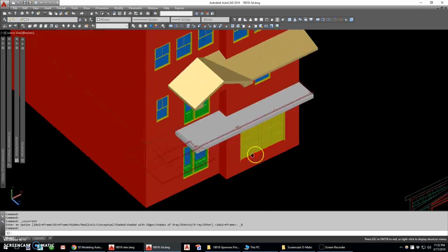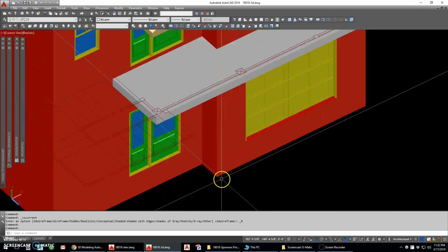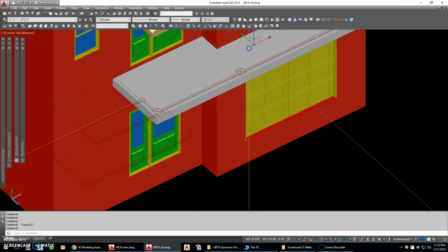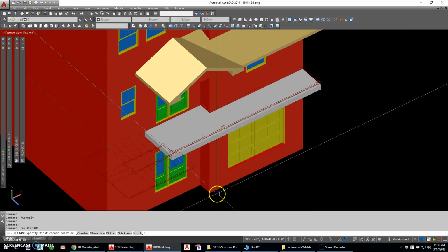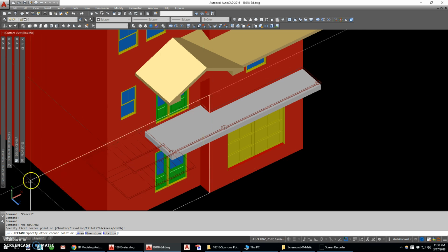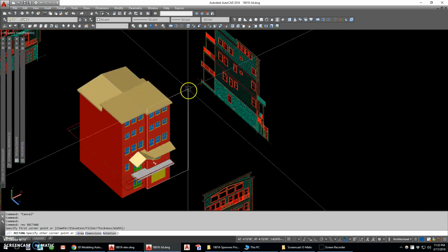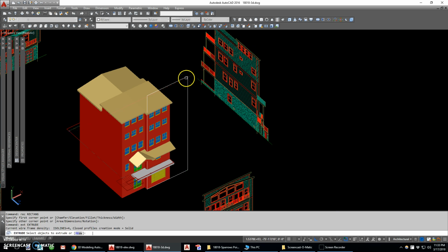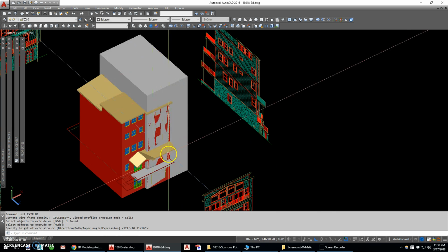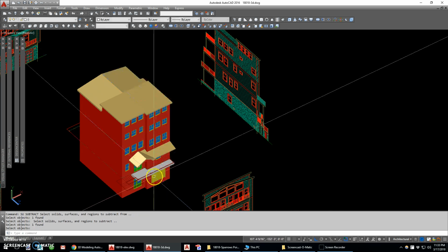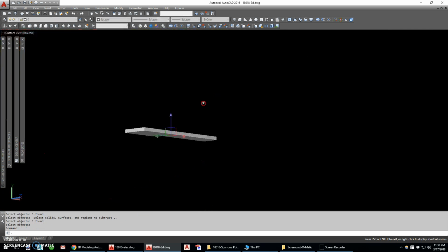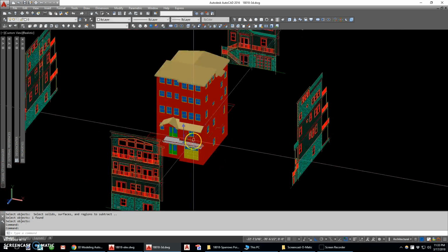All right, now, okay, so what I'm going to do is, again, my geometry, you can see this line, but it's going through my wall. It's better if you don't do that. So what I'm going to do is draw a rectangle here, and I'm drawing on the front of things. Draw it up to some point here, extrude it back, and actually subtract that from my deck. So now I've got my deck shaped correctly.